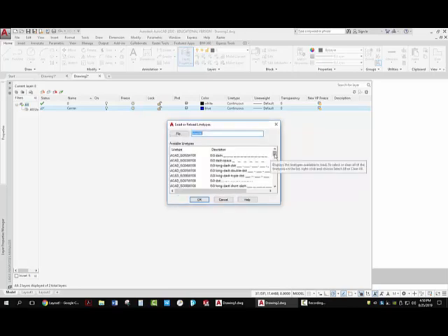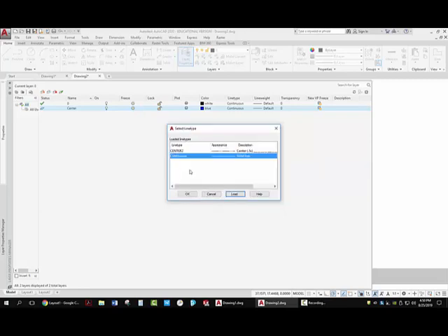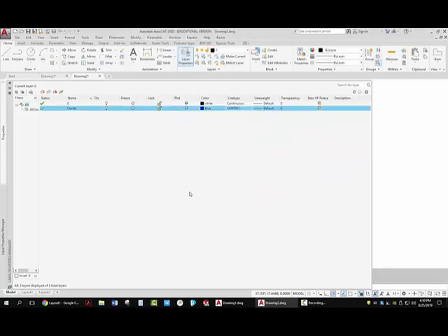I'm looking for a line type called center 2, and it is right here. Now don't pick center X2. That's twice as big a center line, or twice the scale of the center 2. So we're going to pick center 2, pick OK. Now I have to select it again to assign it to that layer. The process of loading the line type is not the same as assigning the line type. When I'm done, I have a new layer called center. It's blue and has a center 2 line type.